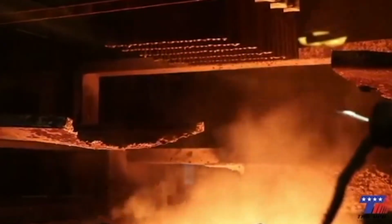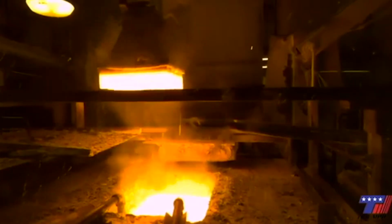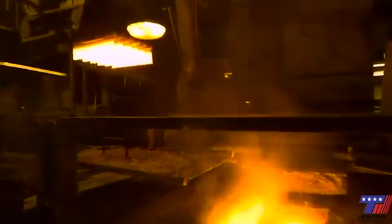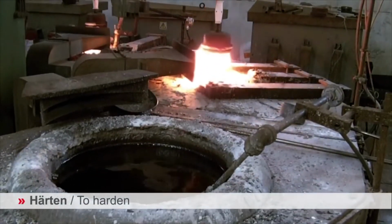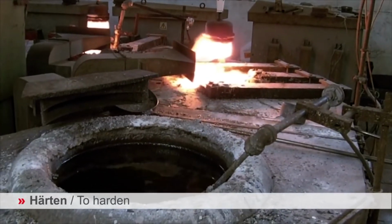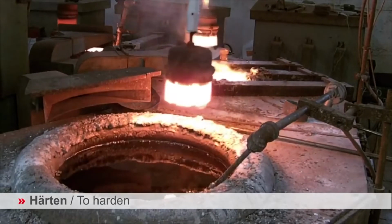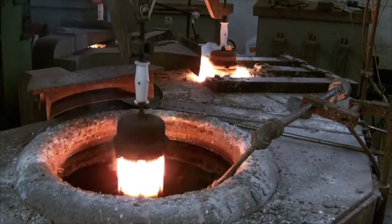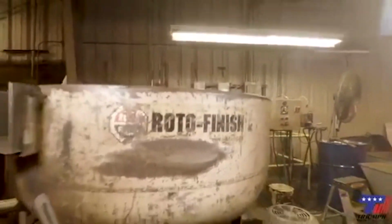The steel rod will then be placed into a hot molten salt bath or a furnace that is set to austenitization temperature. This prepares the rod for quenching. Quenching can make the steel rod much harder but also more brittle due to the percent of martensite. Therefore, tempering is required to increase the ductility of steel without significantly compromising the hardness. More about the heat treatment process will be discussed later in the video.